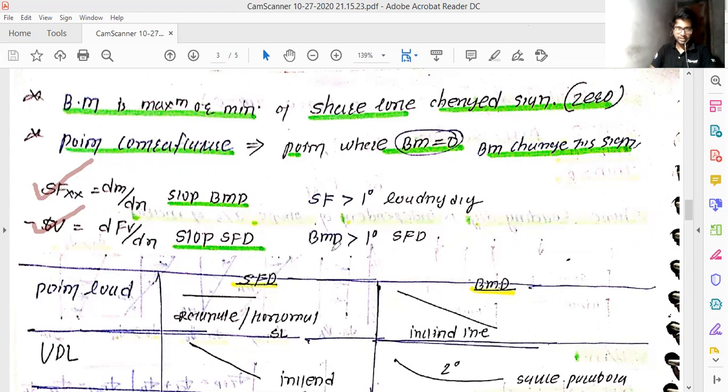As we can also see in the following notation for the different diagrams. So how does it change when the bending moment goes from maximum condition to minimum condition? It changes its sign from positive, a clockwise direction, to negative, and it passes through the center line. So when the bending moment diagram crosses that neutral axis, the magnitude of that bending moment is equal to zero, and that point we call the point of contraflexure.